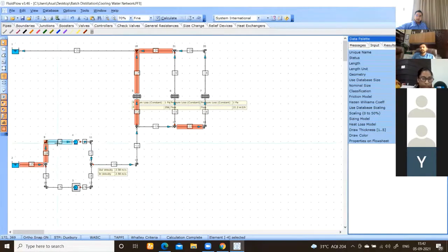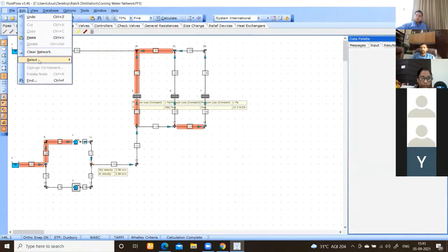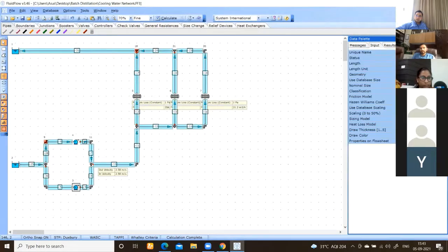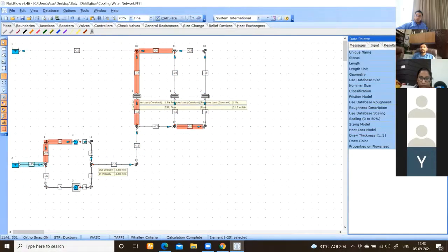So the first step is also not completed, where I had told you to use Hazen-Williams for all the pipes instead of Moody. Sir, I used it for all the pipes. Yeah, but I could see that for this first pipe itself, it was not. Yeah, see, it's Moody. And then the coefficient also.